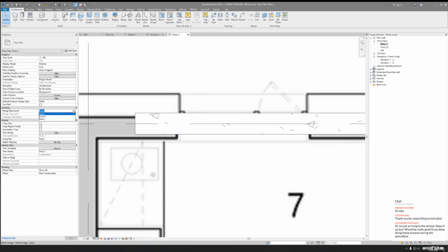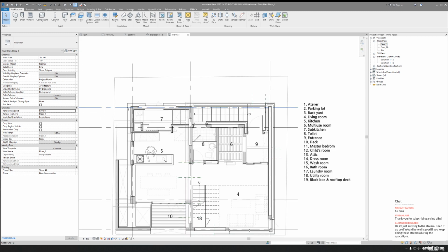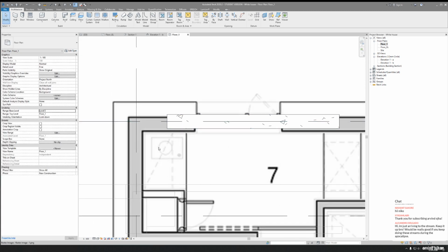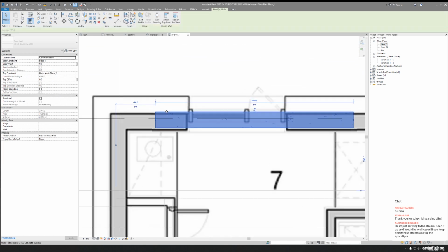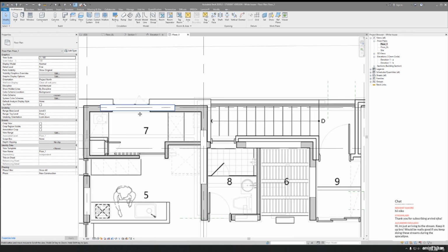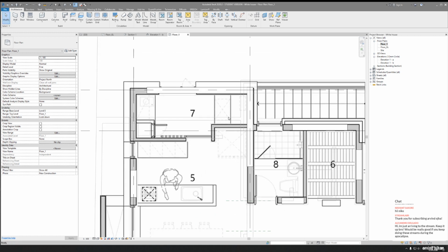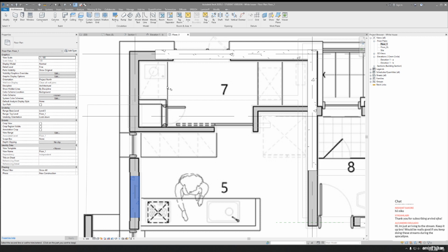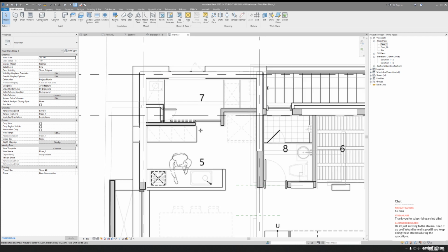First I wanna see what's going on underlay. Let's see what's going on the floor on level 0. Okay, so here is level 0, and where is my wall? Oh, my wall is here, even here. So let's change the position, or maybe we will leave the position on the center line of that. This is better. Let's say this is some mistake in this drawing. Here everything is alright. Let's connect. As you can see, we get the first connecting of our walls. Let's connect this wall. Okay, awesome, and we get the connection already.